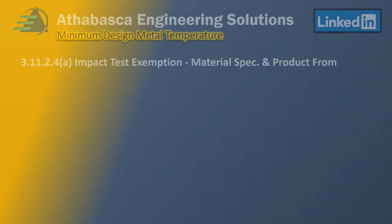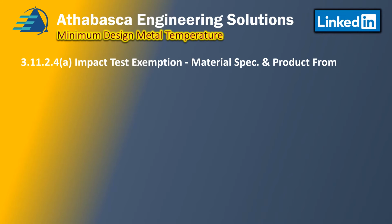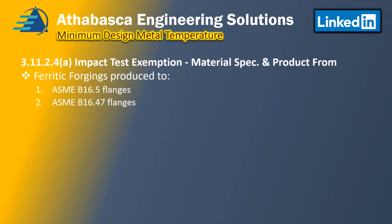So let's look at 3.11.2.4a impact testing exemptions, and let's continue. So ferritic forgings produced to these essential elements: if you have a forging that's a B16.5 flange, or if it's 24-inch and larger, large flanges, you can use a B16.47. That applies to Series A and B flanges. Or if you have forged nozzles like integral type nozzles, then it can apply for the exemption.